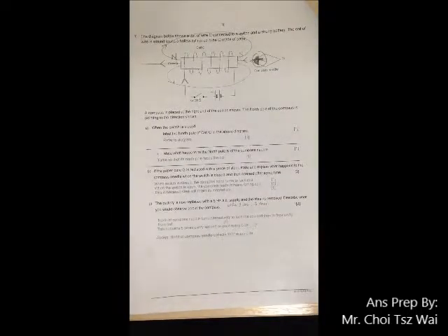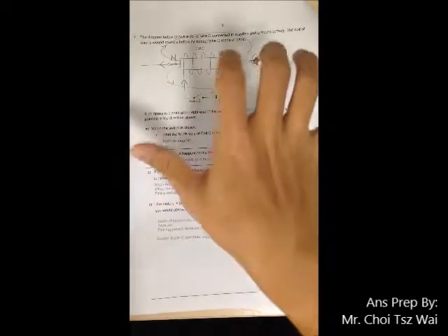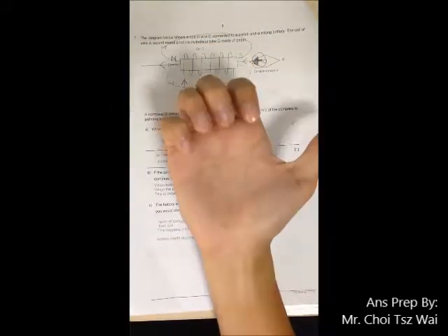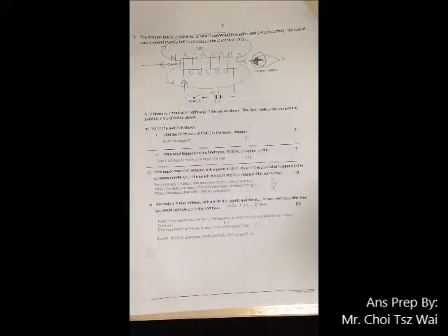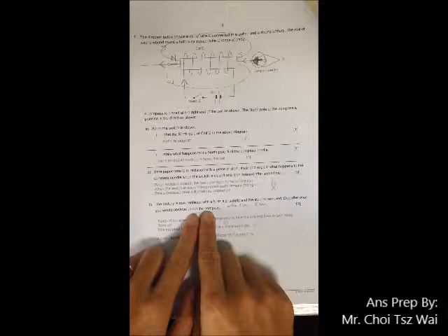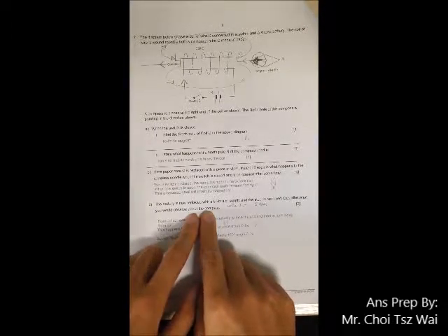So you have to show the marker that you have an understanding of the parameter that is being thrown to you. So what will happen is, use your right hand grip rule. Your north pole is going to flip in 1 second, 5 times, like that. So you have to write it in words, and from the perspective of the compass, because the question asks what you would observe about the compass.